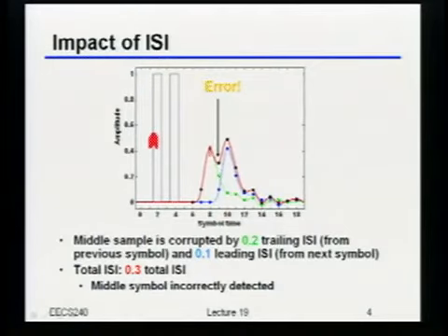Okay? Now, maybe just to point out one thing that should also be obvious. What would set the bound on how much time it would take to get from here to there? Yeah, speed of light, right? So if I told you that I was traveling over a meter, let's say, and somebody told you it got there 10 picoseconds later, you'd say, oh, really? That's kind of interesting, right? So the trick with all these things is, if you know how much delay it took to get there, that tells you how much length you traveled to get from the transmitter to the receiver.